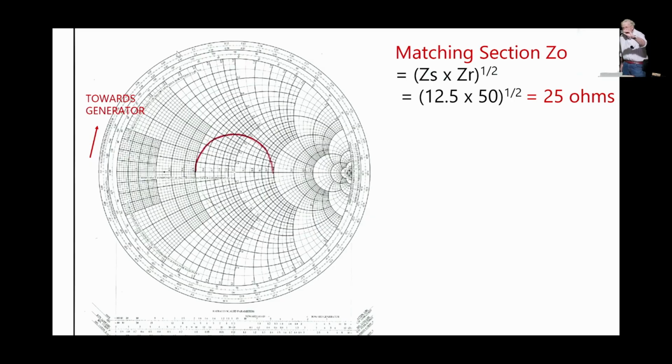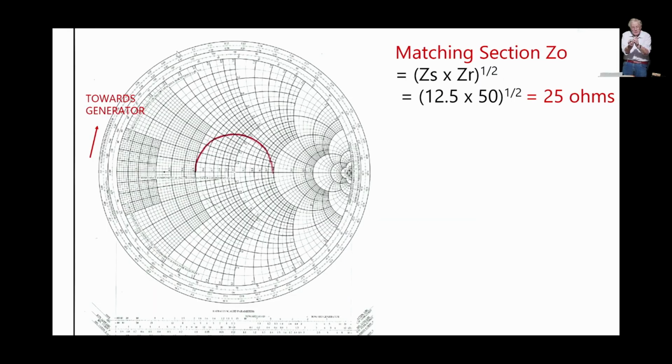And that's the actual realisation of what happened. That's a quarter wave at 23 centimetres. It just so happened that that standard aluminium stock, together with a circular piece of brass from the hobby shop, worked out pretty close to being right.